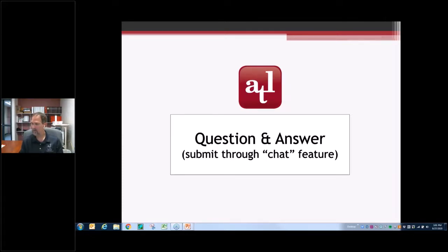Is there an NDT method to know early strength of concrete? There's a couple of NDT methods for early concrete strength. I would say the one that we see used most is the maturity method, and that uses the time temperature history of curing concrete. But for that method, you have to establish a baseline typically in the laboratory.